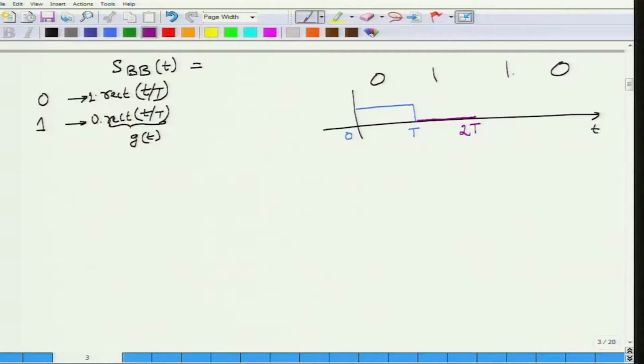Next, you want to transmit 1 again. The amplitude for 1 in our representation is 0. So, you simply continue, although you know that this has ended the transmission for this symbol, because the waveform is the same for the next bit as well. It was 0, this pulse 1, this amplitude 0, next is also 1, therefore the amplitude continues to be 0.